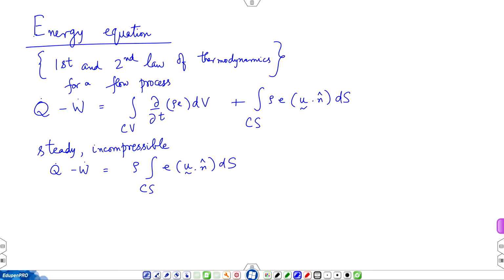So, a fluid element will have to be pressurized to P 1, so it flows into the tube. Now, if P 2 is greater than atmospheric, there is some work exchange, that fluid is coming out at pressure P 2 and then joining the ambient. So, there is some amount of work exchange on that boundary also. These contributions you might recall from your earlier courses. These are all called a PDV kind of work.